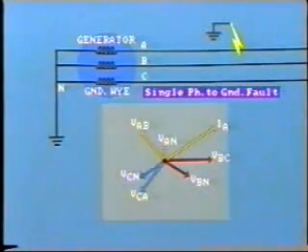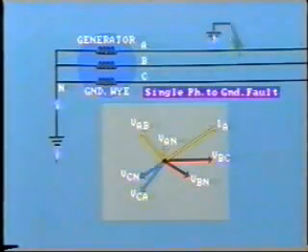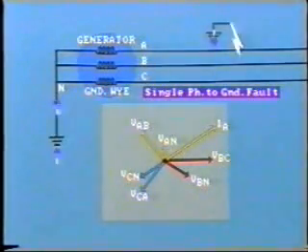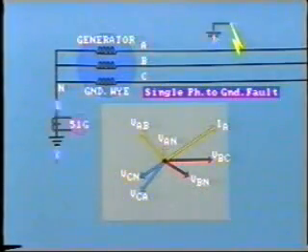With a single phase-to-ground fault, the voltage of the faulted line to ground will fall close to zero at the fault location, and heavy fault current will circulate through this line and return through the earth to the grounded neutral. The resistance of the fault itself plays an important part in determining the value of fault current. Indeed, if this is very high, there may be insufficient fault current flowing to operate the relays.